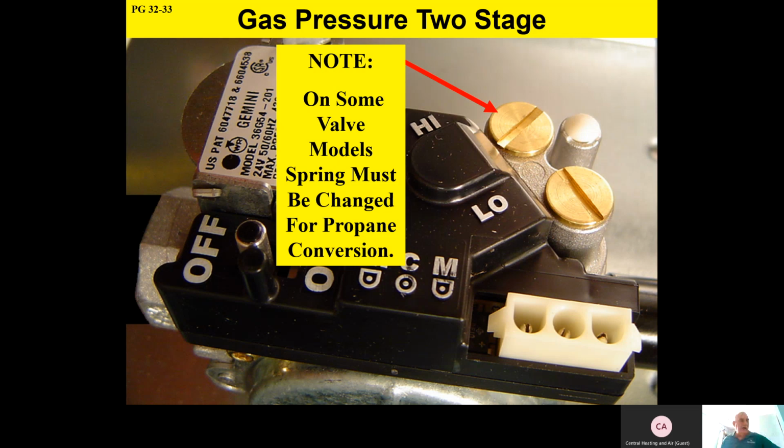I recommend that when you do a propane conversion, that you plan on adding stainless steel burners, because the stainless steel burners are optimized for propane operation. Now, it'll work with the standard burners that come with it on propane, but we find that most of our contractors report that based on the quality of some of the propane they get, they can have more corrosive effect and more water and more condensate being generated with propane.